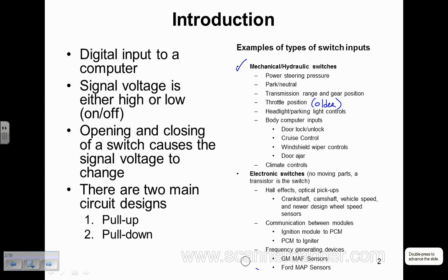Switch inputs. Let's talk about them electrically now. Once we get this down electrically, the designs, then we'll be able to accurately and quickly diagnose any switch input problem on a car. And so there's two main designs. It's pull up and pull down. That's something you want to remember. There's two main design switch inputs. We'll just call them pull up and pull down.